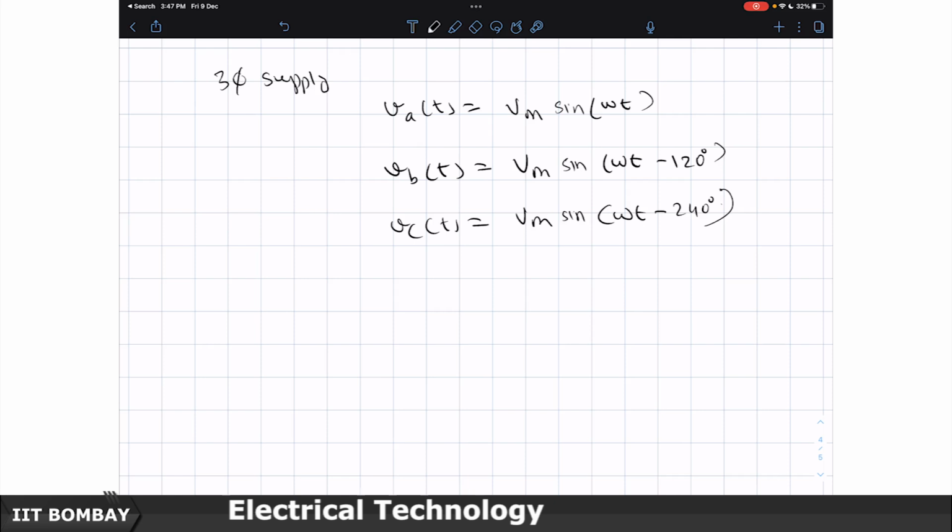Now, this is generated from an alternator or a generator, because the three windings are symmetrical with respect to each other, exactly identical, only displaced 120 degrees in space, having equal number of turns, and they see exactly the same magnet rotating in exactly the same way, because the air gap configurations are not changing.